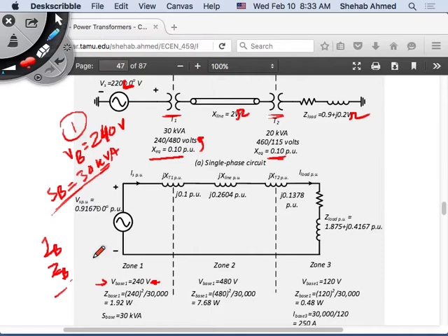So if I know that this generator is rated to 0.1 per unit, and I know that I chose my base such that it's sort of the average operating power of the full system, then I know how much contribution. Without going into the ratings of this specific piece of equipment, I would know what is the contribution of this generator, or how much power this transformer is. It's just a philosophical choice. Yeah, there's nothing wrong with it. Yeah, I mean, there's no right or wrong answer.